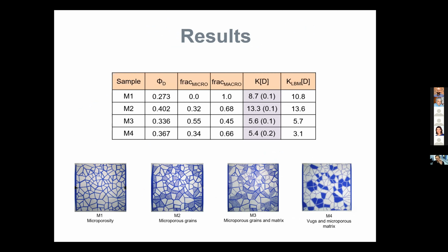On the other hand, if you have microporosity in the microchannels, or thinking like a mud, a microporous matrix in the system filling the big channels, you'll see the permeability go down. So depending on the position of the microporous region, it can influence the permeability of the system in different ways.